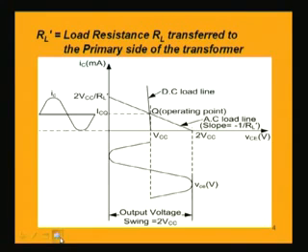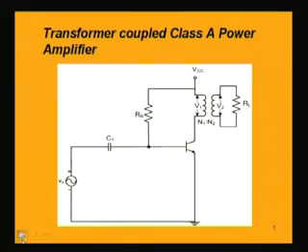So, now if we look into the circuit again, when the DC condition prevails, if we are only interested in the DC condition, then in this circuit, from VCC to ground, this transformer primary has a very negligible resistance. It can be almost assumed to be 0. That is, the transformer primary winding has almost 0 resistance.